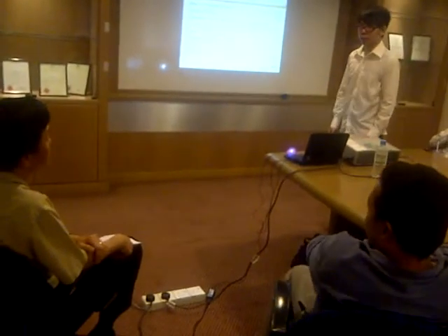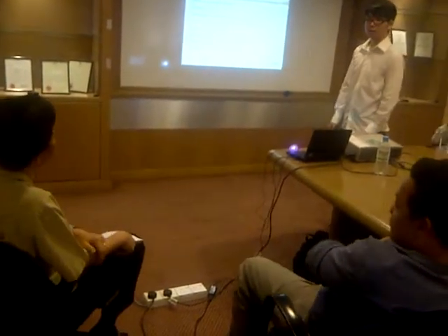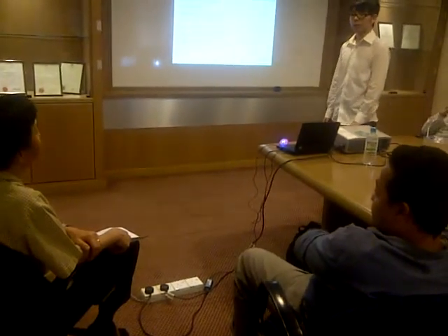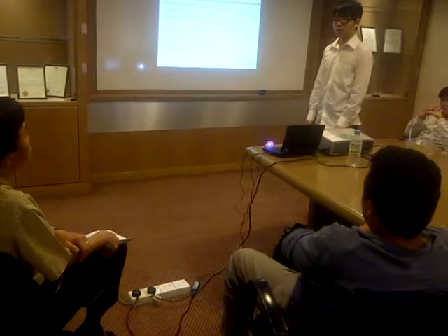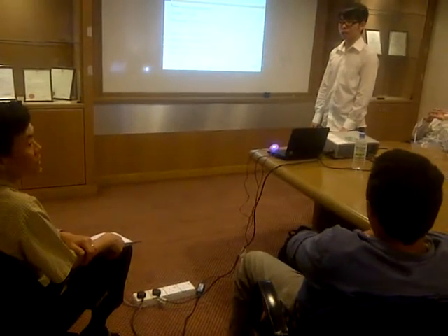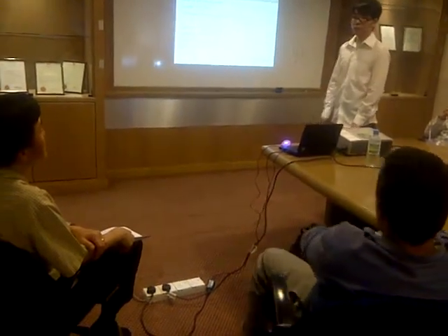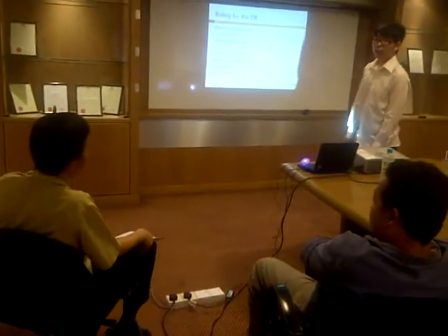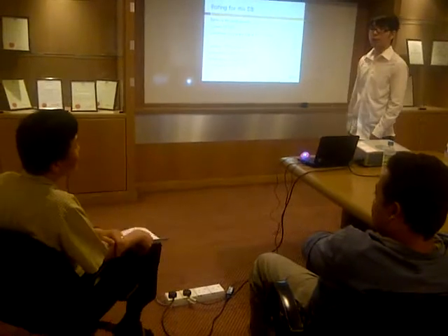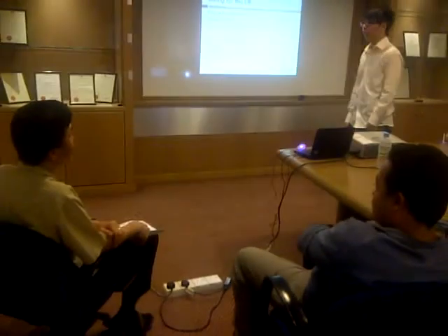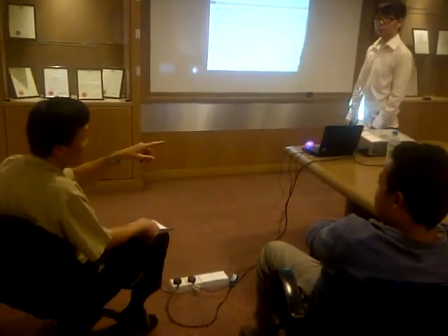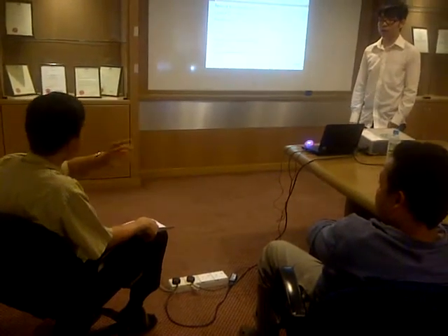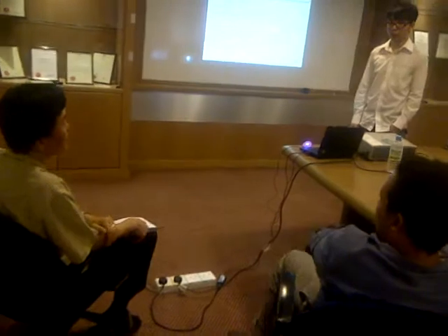You know 1500 divided by 240 is how many amp? About 6 to 7 amp. You know 6 to 7 amp is a 2 horsepower aircon already. So I know definitely the assumption for a PC of 500 watt is too high, not correct. You go back and check.